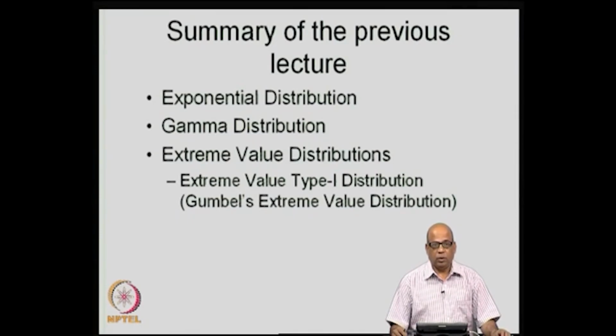The gamma distribution is in fact a family of distributions, and you recall that exponential distribution is in fact a special case of gamma distribution, where we put eta is equal to 1 in the gamma distribution PDF to obtain the PDF of exponential distribution. The gamma distribution is typically used for rainfall distributions across several time frames. In many cases, we use the gamma distribution also for seasonal rainfall, monthly rainfall and so on.